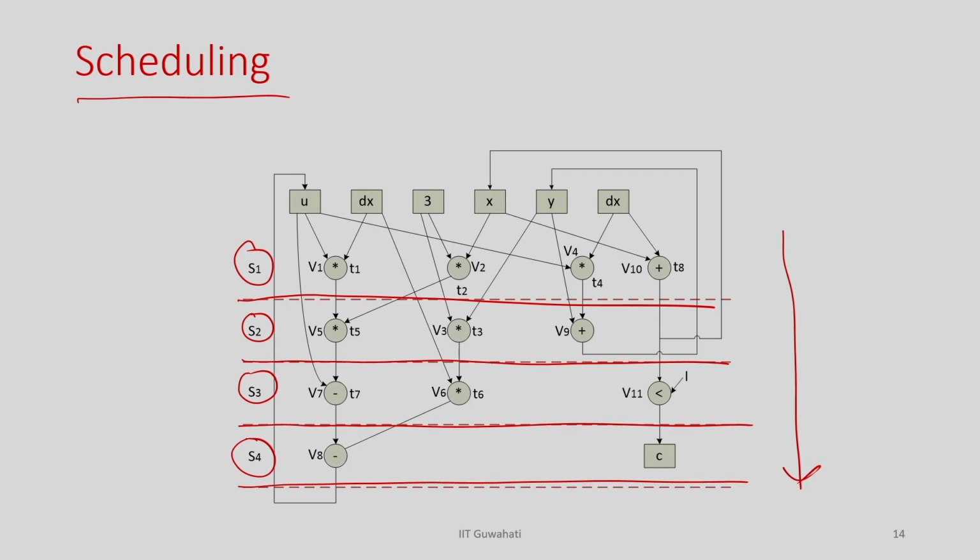So, this is satisfying the data dependencies. You can see here that when I am trying to schedule this operation, both its predecessor operations are already done, already executed, right. So, that means scheduling determines the operation for each time stamp, that means it is assigning a time stamp to each operation. It determines in each clock what operations are going to be executed. Okay. So, this is scheduling.